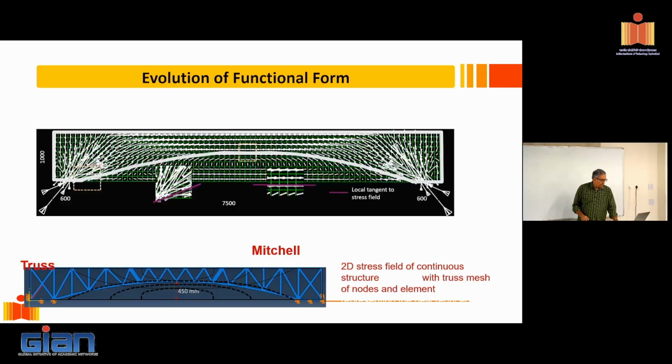And then, of course, to develop a structural system inside this compression form, there are several ways of doing it. So there people follow a process called topology optimization. If you've heard of topology optimization, it's a mathematical exercise, right? So I can give you this rectangular domain, and you can feed it into this optimization subroutine. These are complex optimization subroutines, which will basically take away material wherever the stress is low. And you keep coming up with a revised geometry after every iteration.